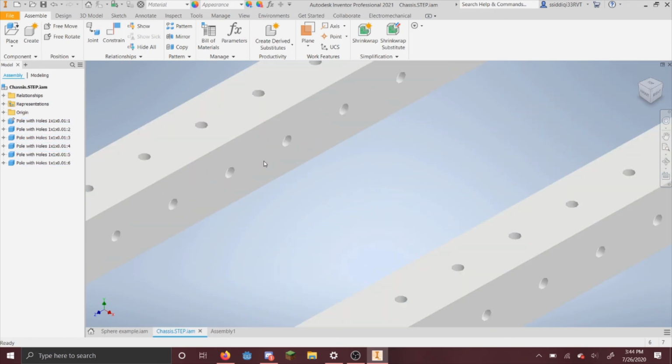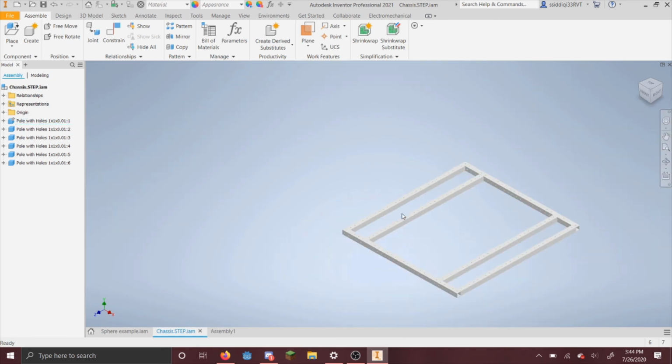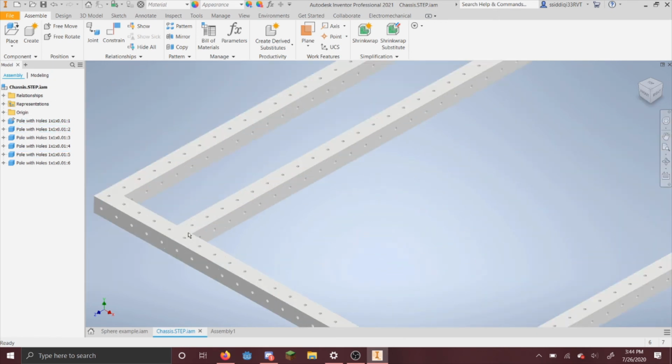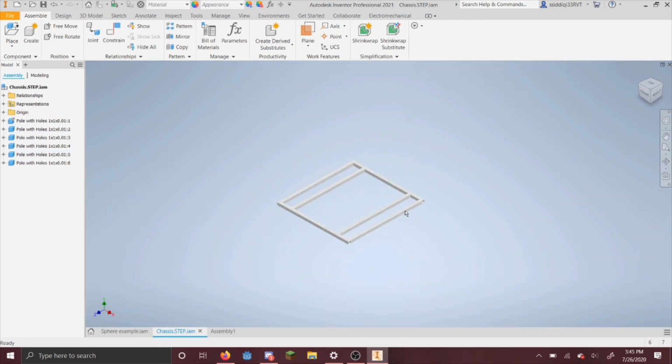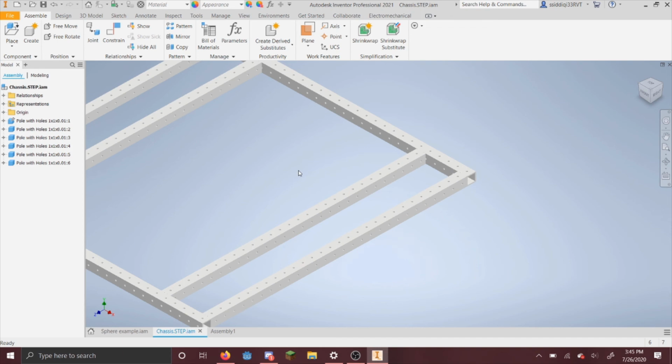All of them are square, rectangular. All the faces that the mate is used on, all of them are flat. You don't see any curves in this, and that's where mate and flush shine. They're best used in an instance where the two faces can be conjoined easily just on a flat face.